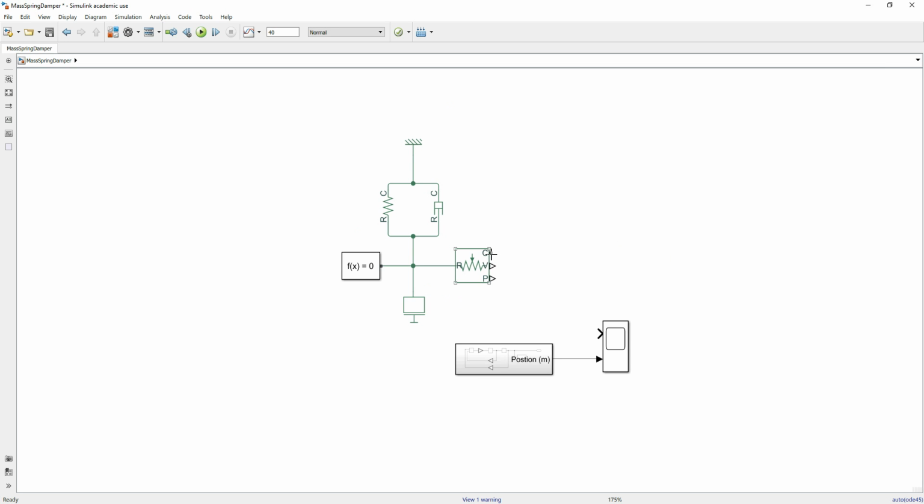You'll notice that the output here needs to know what its reference point is relative to. Now, if you remember in our first simulation in Simulink, what we were relative to was 0. We were assuming our initial point, our ground point, would be 0. So I'm going to right click and drag a copy of this and connect these two up. This now grounds it. In any of these types of simulations, there's always the possibility of crashing, so make sure you hit save. I'm going to do it myself.